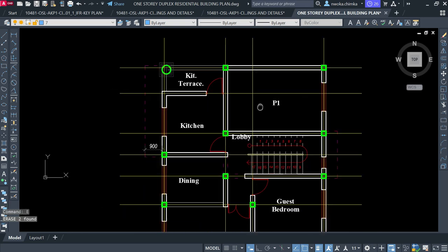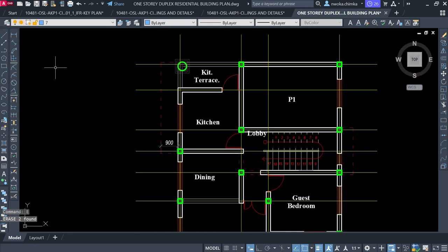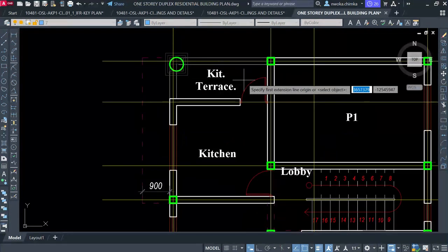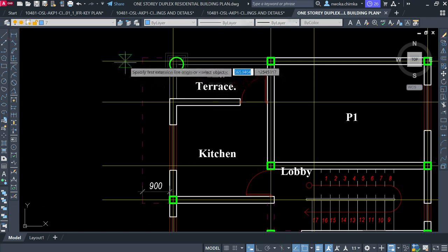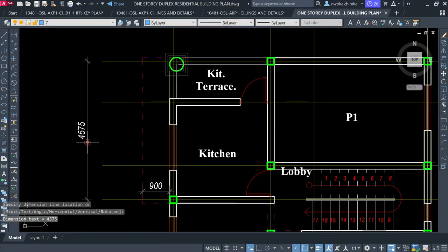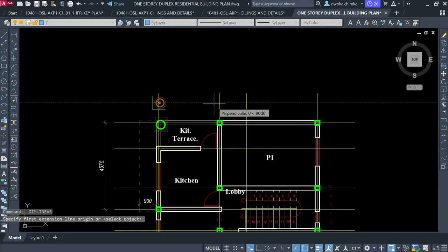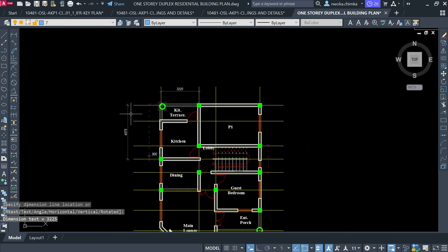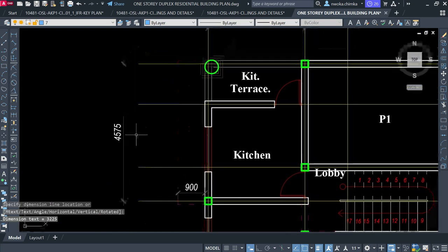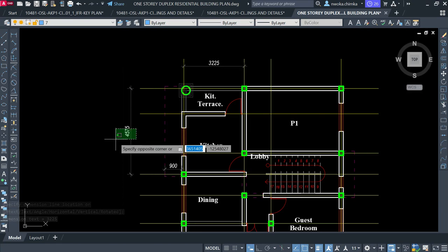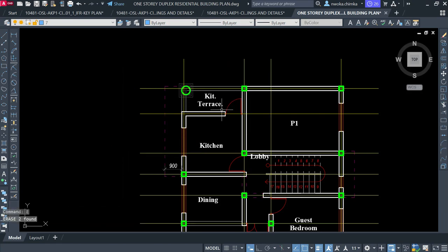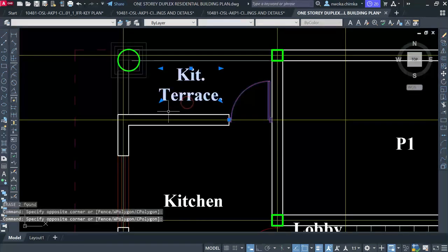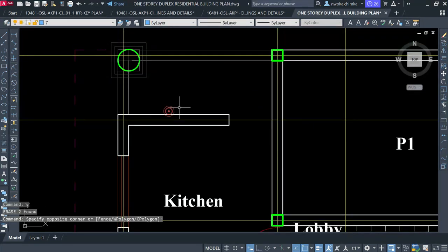Okay, so here again, I can check this panel. Let me see if I'll choose this terrace and this kitchen as a panel. First of all, before you choose, check if they are within the guiding principles. So this to this is less than that. 3 times 4.5 gives us around 12 point something, or let me say 13, which is less than 30. So I'll take it off now and remove this, and take this as a panel also.